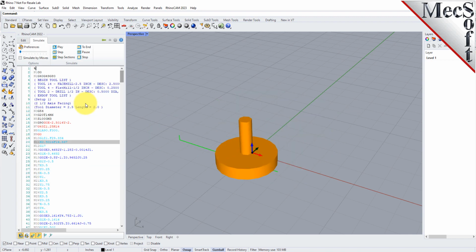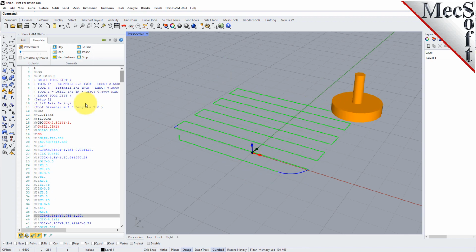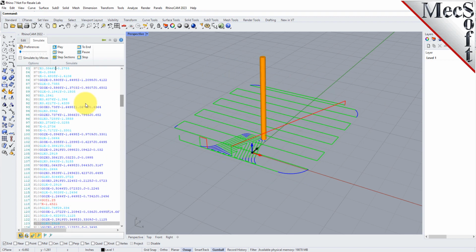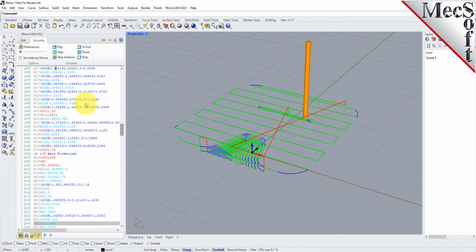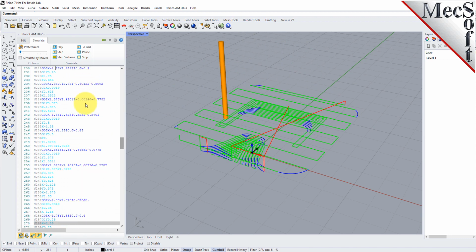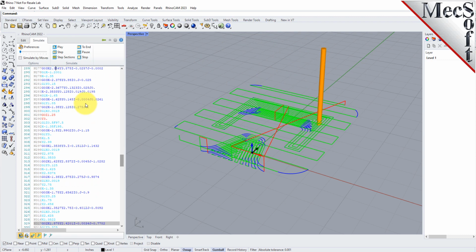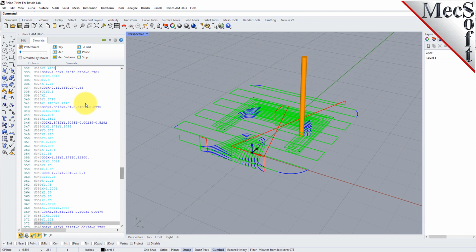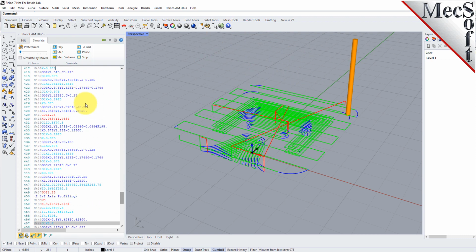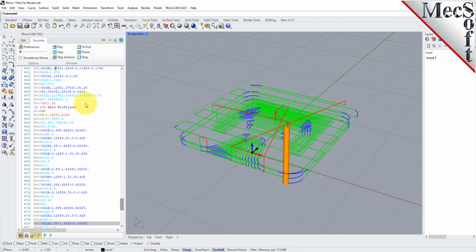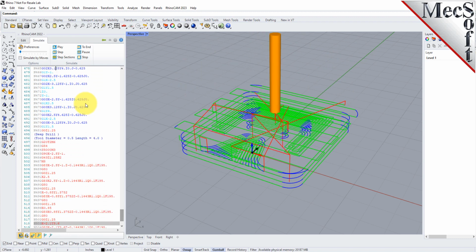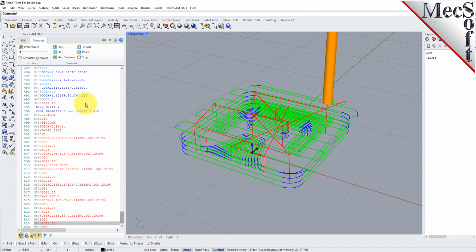And you'll see that the G-code is loaded into the editor, the Simulate tab is activated, and it's running through the G-code file, displaying the correct tool as it goes through each tool motion. Also, which is a cool thing to do, you don't have to run the entire simulation.